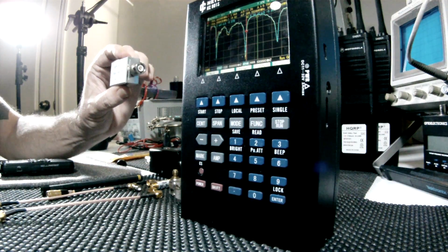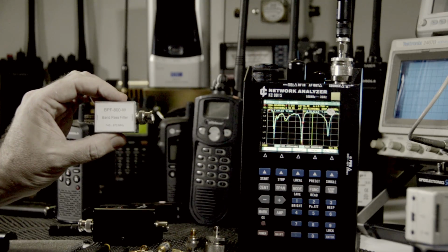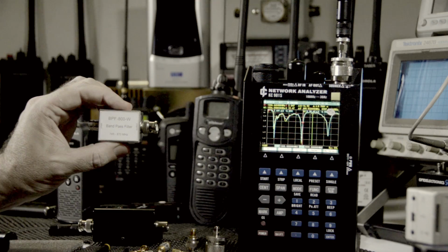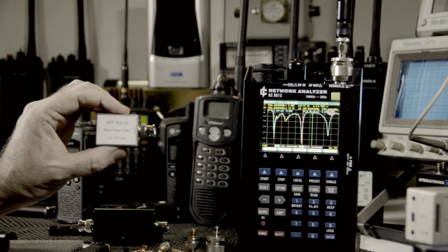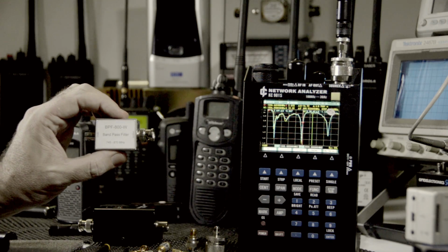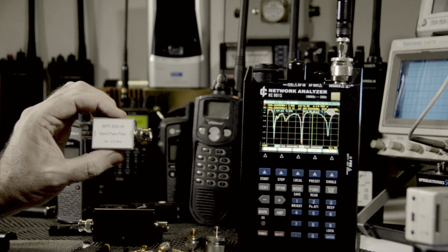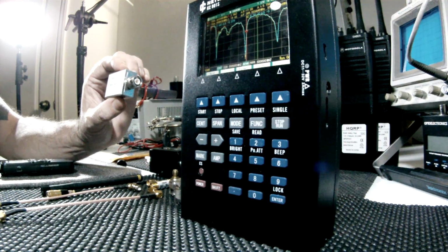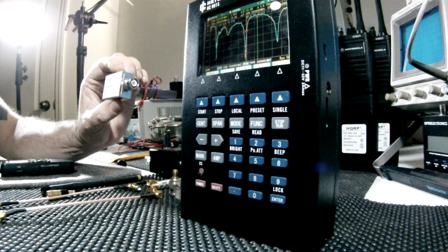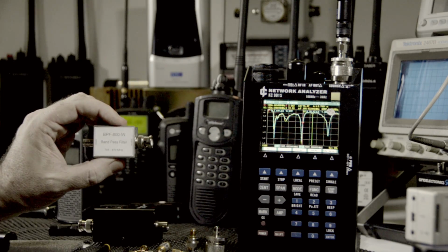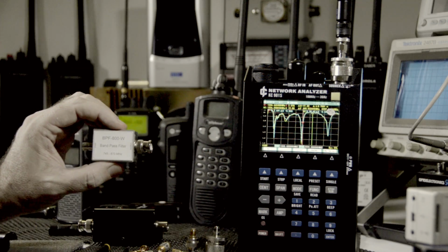You have your bandpass filters, and they allow a certain frequency or frequency band to pass, and then you have notch filters or stop filters which stop certain frequencies, and these can be very important to attach between your antennas and your transmitters or receivers to either pass certain frequencies that you want to pass or to block out frequencies that you do not want to pass.